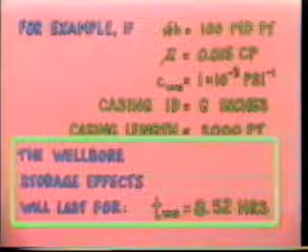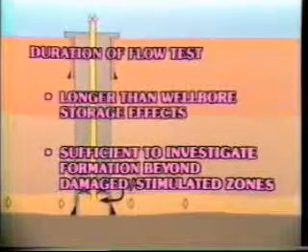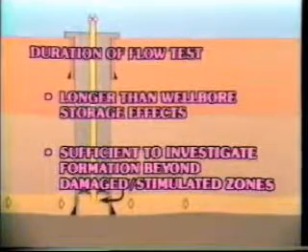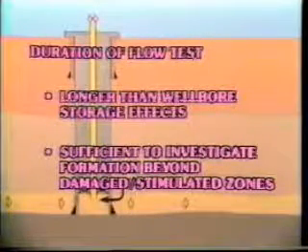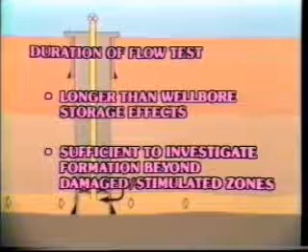However, had there been 3-inch ID tubing on a packer in the hole, the storage time would have been reduced to less than 1 hour. In most cases, then, the wellbore storage time is short. The duration of a flow test, especially for the flow period of an isochronal test, must be long enough to investigate the formation beyond the near wellbore damaged or stimulation zones.